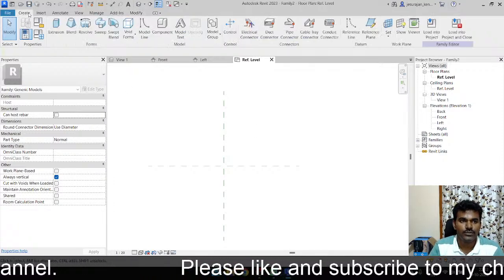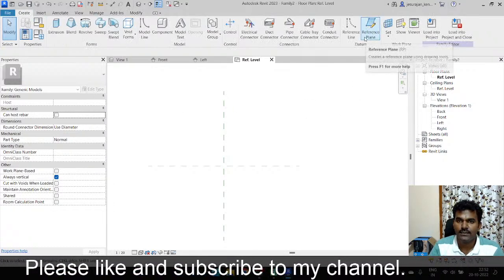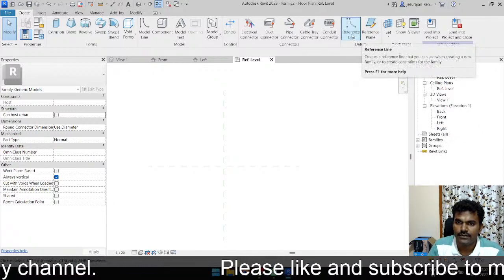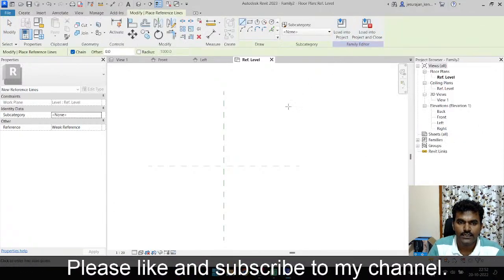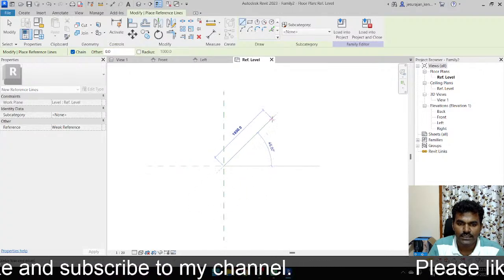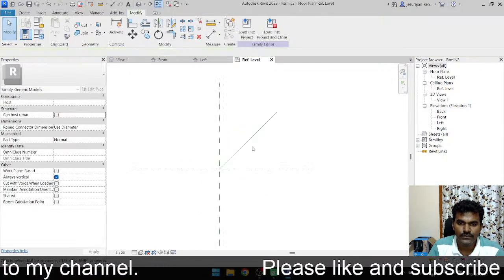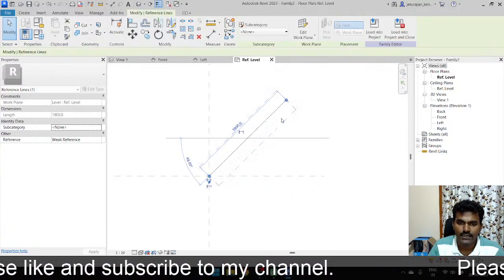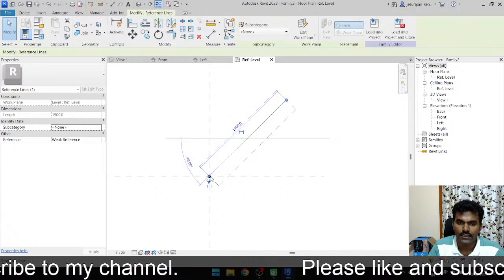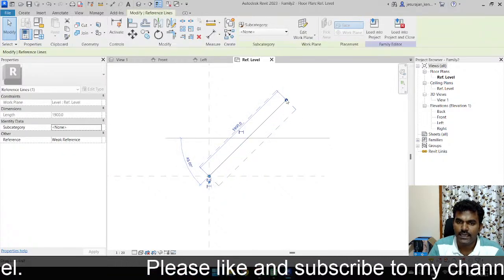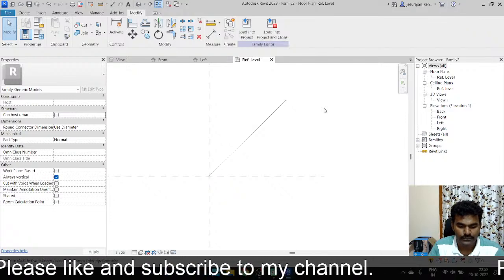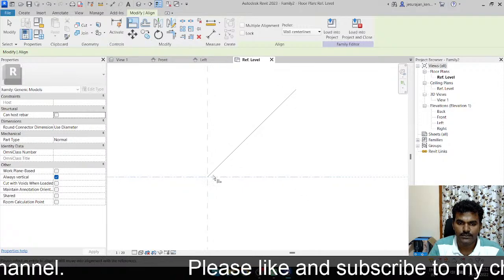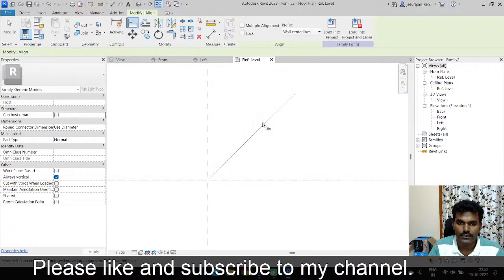Okay, let's go to create. Instead of a reference plane, I think for the first time we are going to create a reference line. I'm just going to take the reference line here. So for the first time we are using a reference line. Why am I taking a reference line? Because I can lock the starting point and ending point. I'm just going to align the reference plane with the reference line.